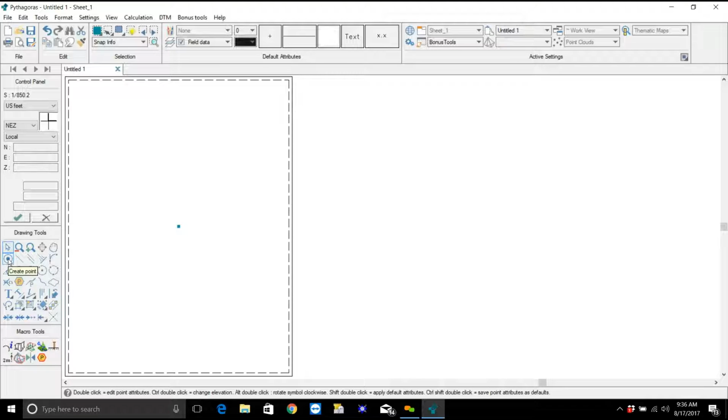So I'm going to set some other points on the screen. Go back to my point tool. But this time, I'd like to just set these points around this one, and I don't want to have to confirm each one of them. I'm not going to set specific coordinates, so I'm going to turn off that little green box by clicking on it. And now I'm ready to set some points. The point tool is highlighted, so I'm going to set a point, let's say over here. And notice I'm not having to hit that green checkbox each time, like so.